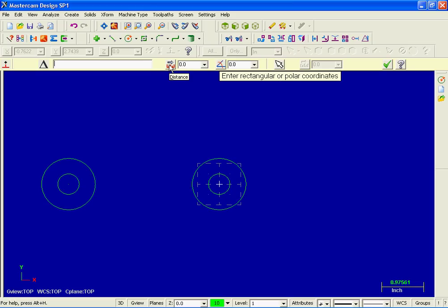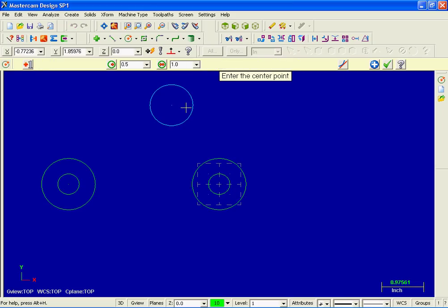So up on the ribbon bar, I'm going to click in the white space for distance. Now on my drawing I've got a radius of 2.215, so I'm going to input 2.215 and then hit the tab key on my keyboard, and now I'm transported over into the angle section. I'm going to type in 120 degrees and hit enter, and there's my circle. I'm going to hit apply.